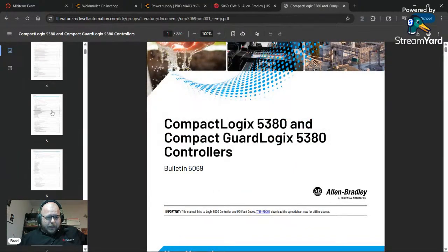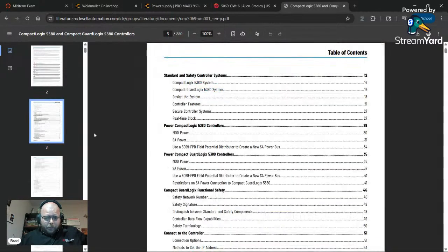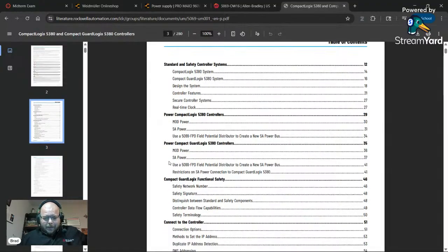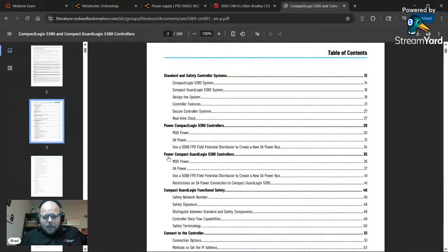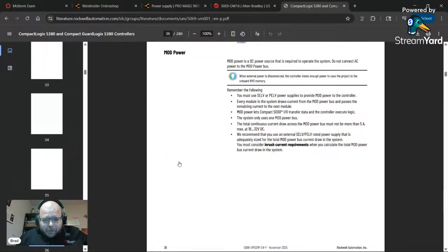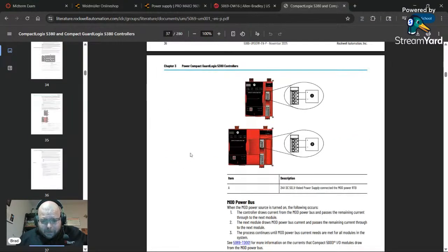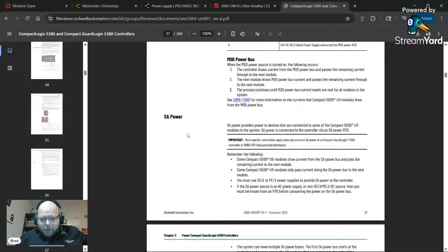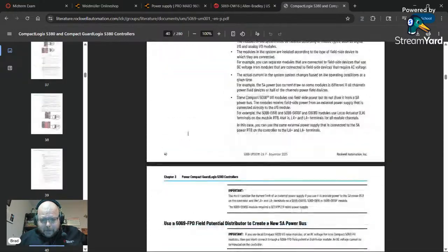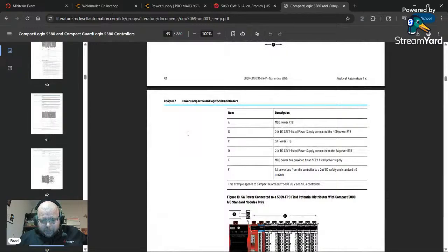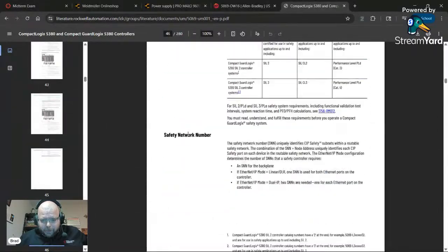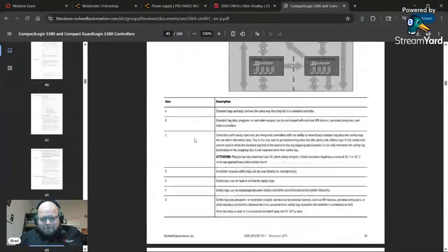The wiring is the same regardless of what size. The L306, 310, 320, that's basically the size of the memory. But we need this module power. Yes. So this is what I'm talking about. You can see right here, 6 terminals, 4. You need to order both a 6 and a 4 for every PLC. But I want the wiring diagram. I want to see which is which because I don't remember off the top of my head where all the power goes. I just plain don't.